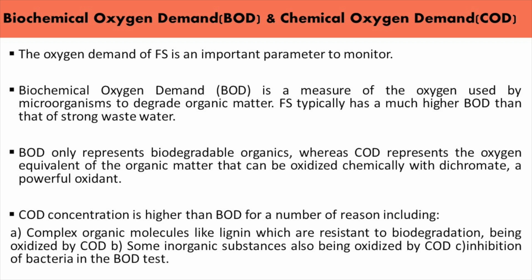Biological oxygen demand, that is BOD, is a measure of oxygen used by microorganisms to degrade organic matter. The standard method for detecting BOD involves incubation at 20 degrees Celsius for 5 days. Wastewater is considered to be weak, medium, strong, very strong respectively at BOD 200, 350, 500 and 750.